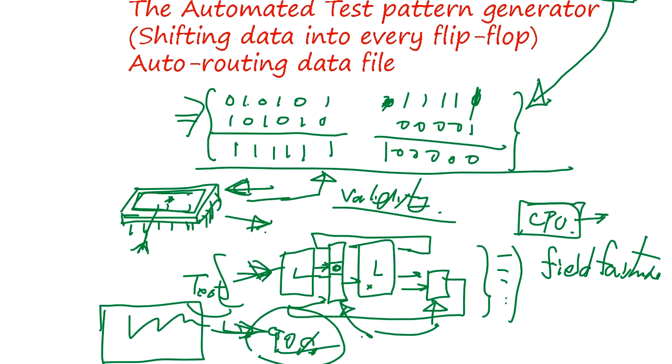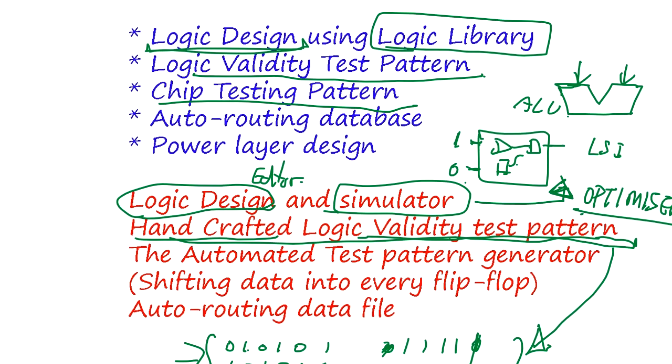So what happened is, for this kind of chip defect test, functionality test pattern, by experience we know that you use a shift function to shift some random data into the registers. So the test pattern for the logic input, and also the test pattern for the data shifted into every register element, is going to increase the coverage of the defect test very well. Okay, this is by experience. It's very hard to theorize why that is. Long experience tells us that's the method we have to use.